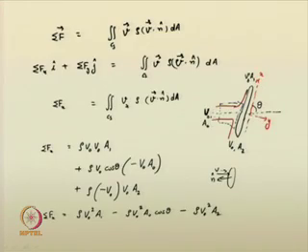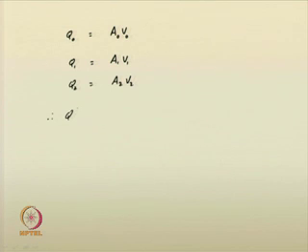You can suggest that q 0 is the discharge at this particular inlet, and we are assuming steady state condition. So, discharge is nothing but a 0 into v 0. Similarly, q 1 is equal to a 1 into v 1, q 2 is equal to a 2 into v 2. So, we have assumed that there are no impact losses. Therefore, from the continuity equation you know that q 1 plus q 2 is equal to q 0. Okay.